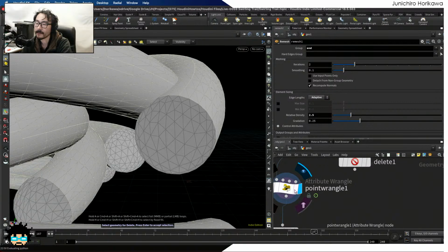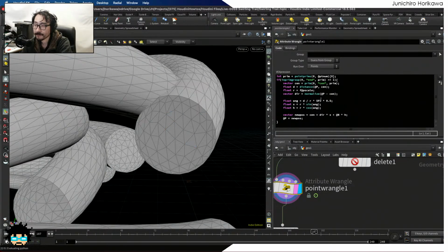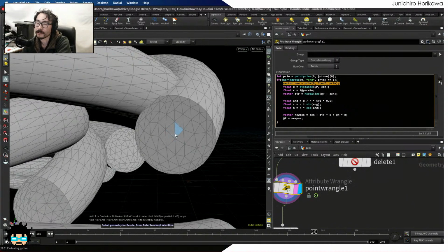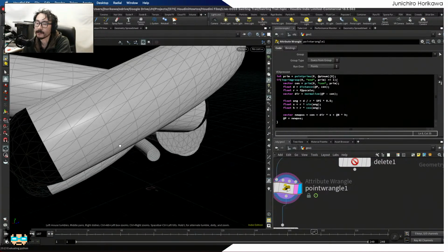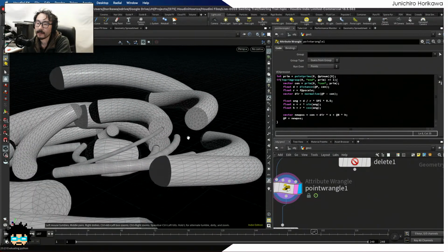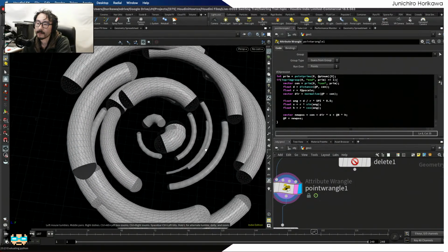Then when it comes to here, for each point that belongs to the end cap, you can access that center attribute, which is always this center point at the end, and using it as the center point, you can calculate the radius from the center to each point by calculating the distance, like this one. Then the rest of the stuff is as I said. Just use it for the calculations, and checking what it looks like.